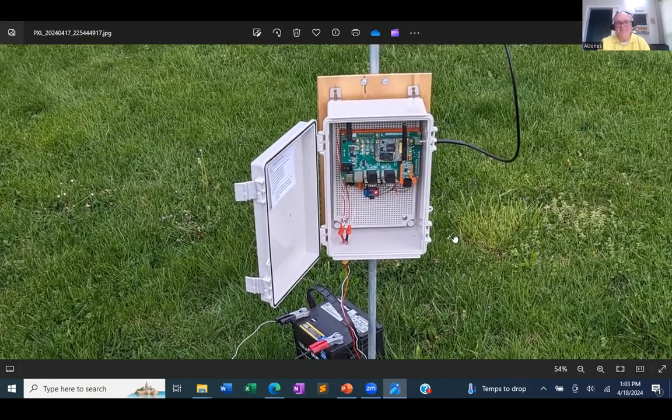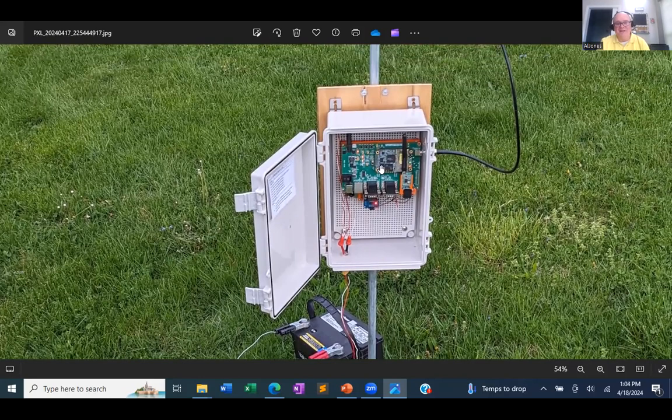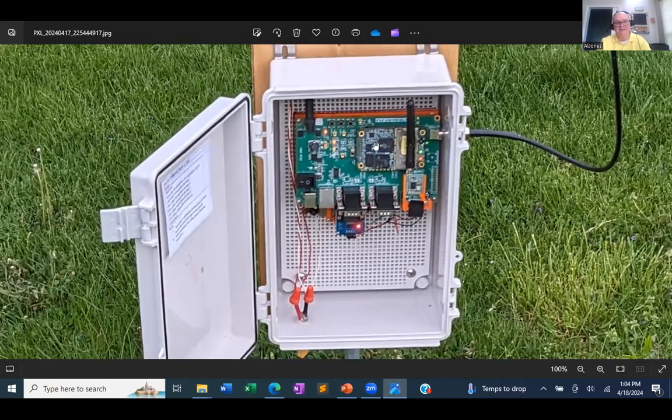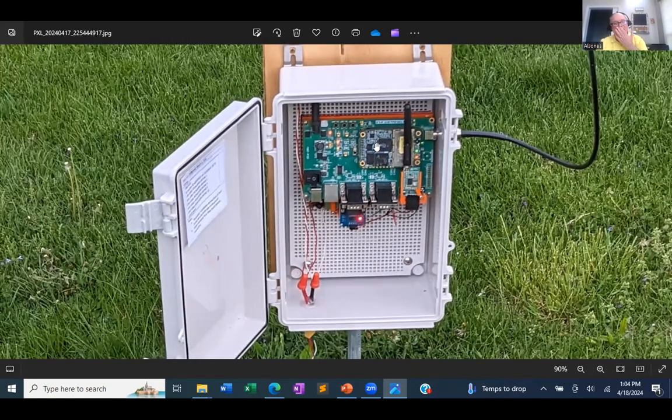Anyway, not very complicated. As Jeff said, the GPS is actually this unit itself, and the rest is a development board. Since it's the base station, it's sending out correction data. The correction data is going to this UART, being fed into this 3DR radio that doesn't have a wrapper around it. I haven't mounted the antenna outside, so I'm sure at some point that inhibits the strength of the signal somewhat.